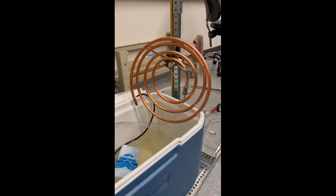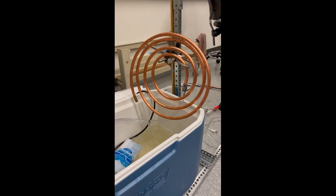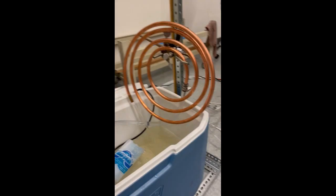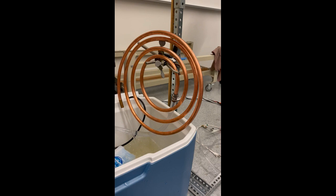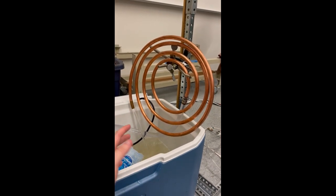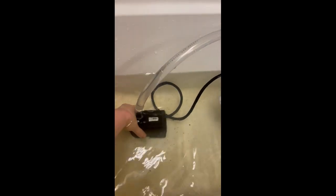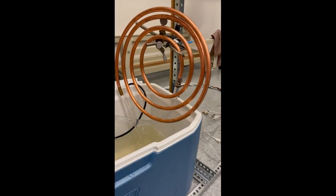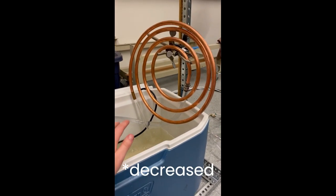Now, some of the parameters that determine how well or not well our air conditioner is able to conduct heat from the environment include the diameter of the pipe. We can also manipulate the length of coils. With more coils, we have more surface area in contact with the environment, and so that would also increase our overall heat transfer. And then finally, we can also increase our pumping power. So here is a medium-sized submersible pump. However, if our pump was stronger, we would get, again, an increased mass flow rate through the coils, and that would also lead to an overall increased rate of heat transfer.